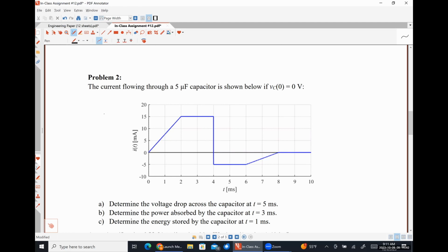The expectation there is that you remember the capacitor should look like an open circuit, and you need to find the voltage drop across that open circuit in order to determine stored energy. And the inductor will look like a short circuit, and you need to find the current flowing through the short circuit in order to find the inductor stored energy. So I believe I answered that question. And again, all of that bears out based on what you should see on your practice exams.